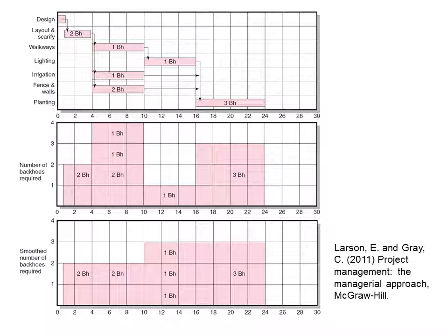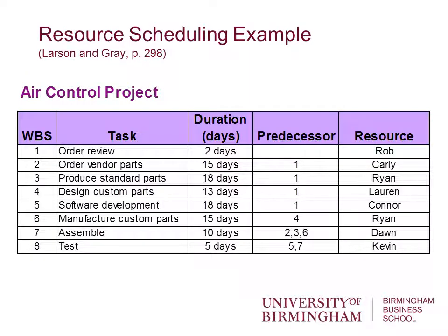Okay. Whereas in the second example, up to week 10, we have 2 machines on the project site being used continuously, and then from week 10 to the end of the project, we get a further machine, and we have 3 machines on the project site for the remainder of the project. Okay, so hopefully you can see that this is a much more efficient use of resources throughout the duration of the project. That's why smoothing is so important. And here, what we've done is use float to shift one of the activities in order to create this smoother distribution of resources throughout the project.